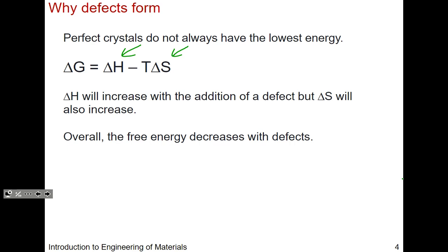So with impurities, you can imagine that's affecting your delta S. If you have a sea of copper electrons, and then you put in one nickel atom, you've changed the entropy, you've increased entropy, because where is this nickel atom going to go? It can go anywhere, right? It can totally disrupt the order of the system. So if it's increasing delta S, it's going to increase the negative component, right, of delta G. It's going to make delta G more negative. So imperfections are more thermodynamically favorable. Okay?